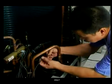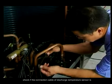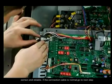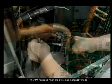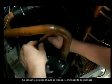Step 1. Check if the connection cable of the discharge temperature sensor is correct and reliable. If the connection cable is normal, go to the next step. If P0 or P4 happens when the system is in standby mode, the sensor resistance should be incorrect and needs to be changed.